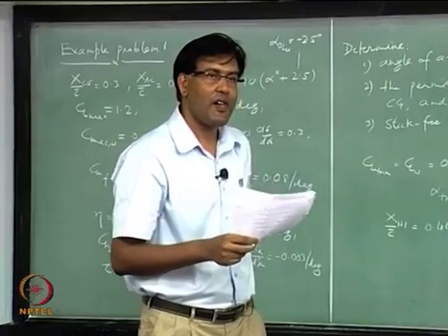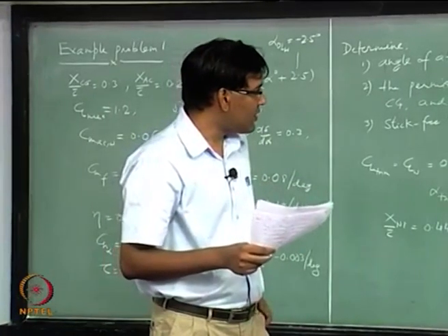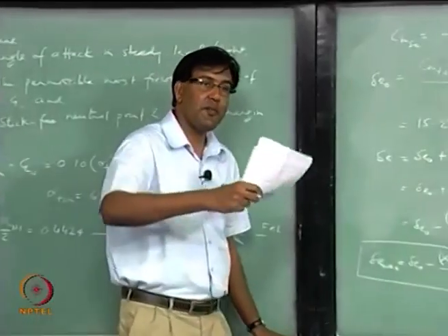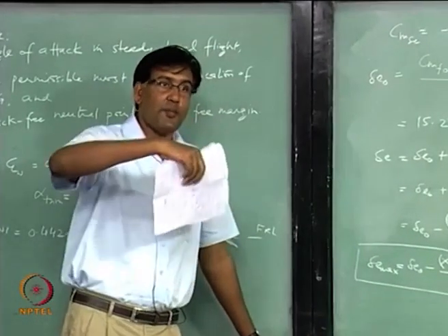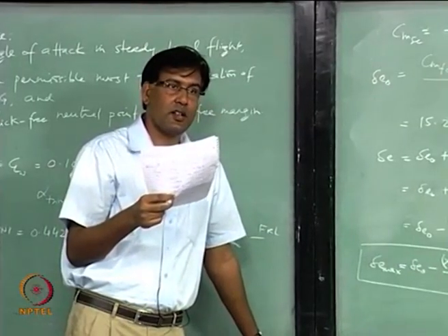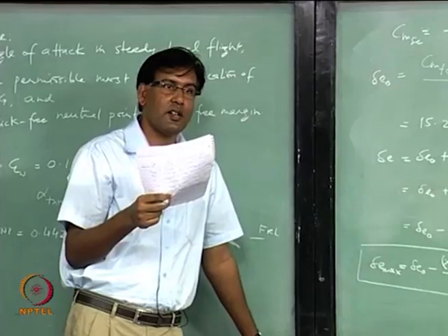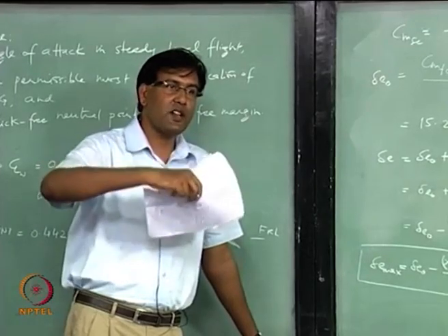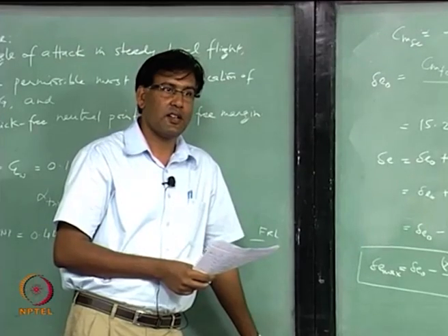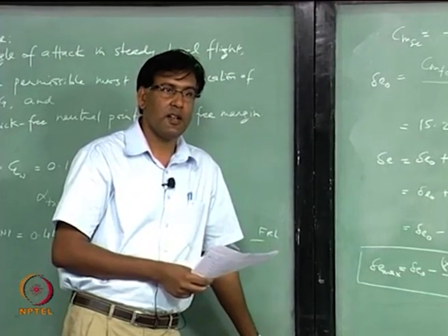Also if CL is maximum, then if you substitute CL max, then delta E will be minimum if you put a minus sign there. If you see that boxed expression, delta E is maximum up. Up is what? Up is negative. Up deflection of elevator is negative.